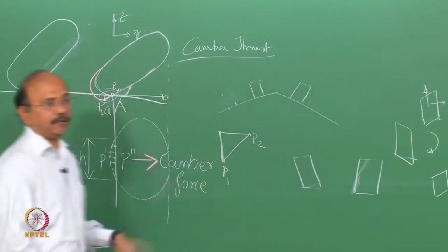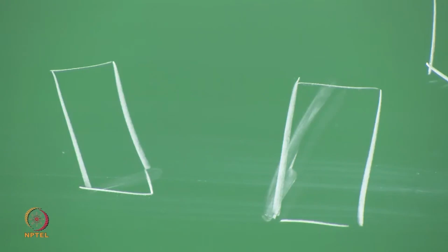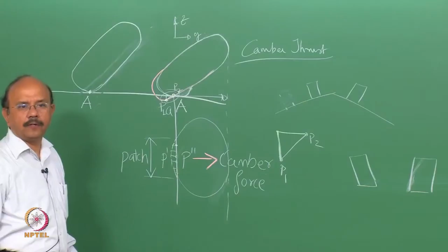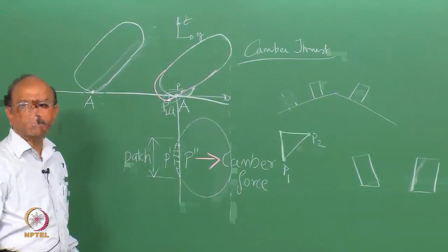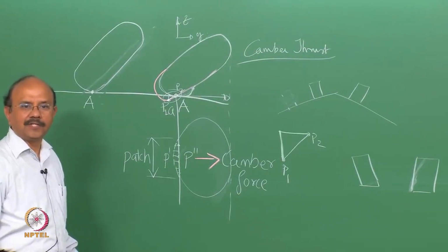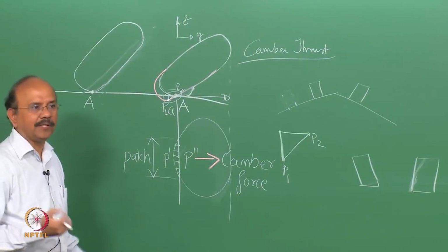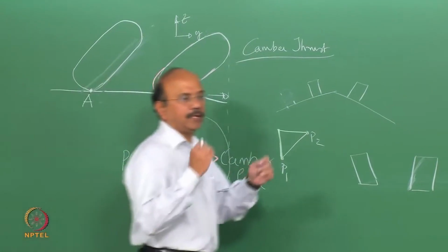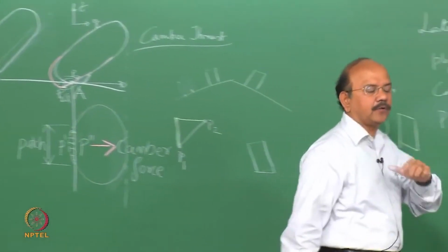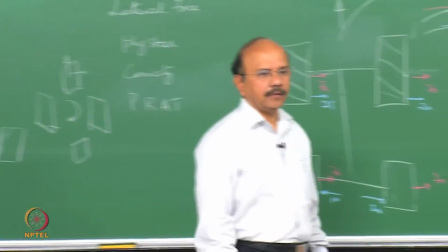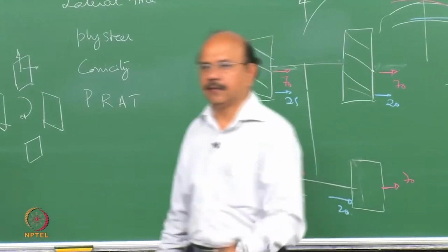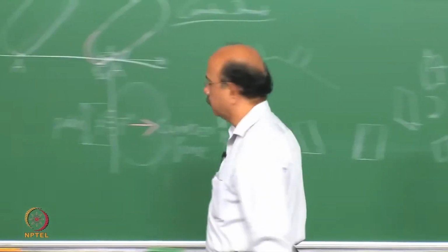I'm just exaggerating. It's very important for trucks, and it's very important that the truck manufacturers look at what their camber is. They give a big range, but that would have a lot of effect on tire wear. And it also goes with the road camber.